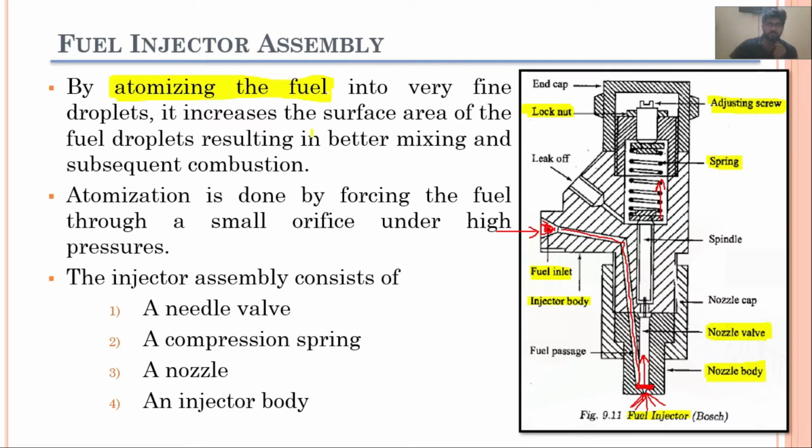So by atomizing the fuel into very fine droplets, it will increase the surface area of the fuel droplets, resulting in better mixing, and it will give you better combustion as well. So this is what I was talking about, that atomization of a fuel will give you better mixing. Okay, atomization is done by forcing the fuel through a small orifice under high pressure.